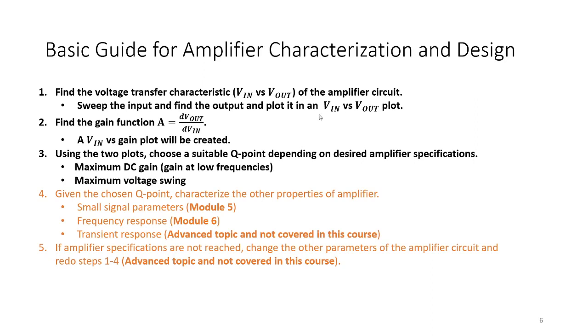So you just do DC analysis, just like what we did in module 4.3. That's where we're just going to repeatedly do that. And then we find the gain function. The gain function is just the derivative of the output with respect to the input, because as you remember, it's just V out over V in.